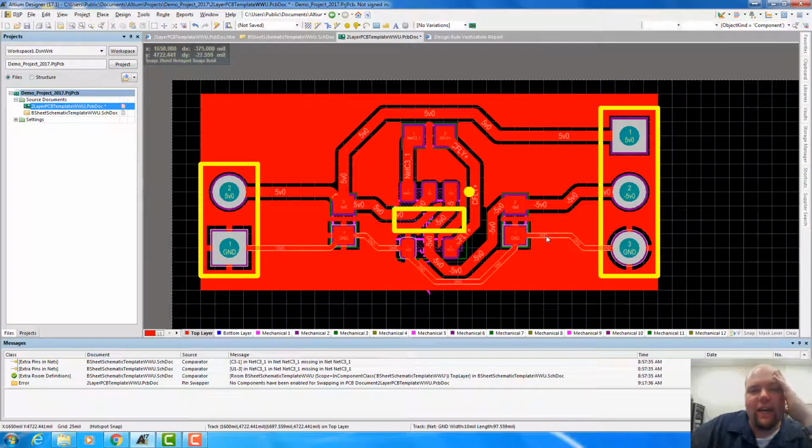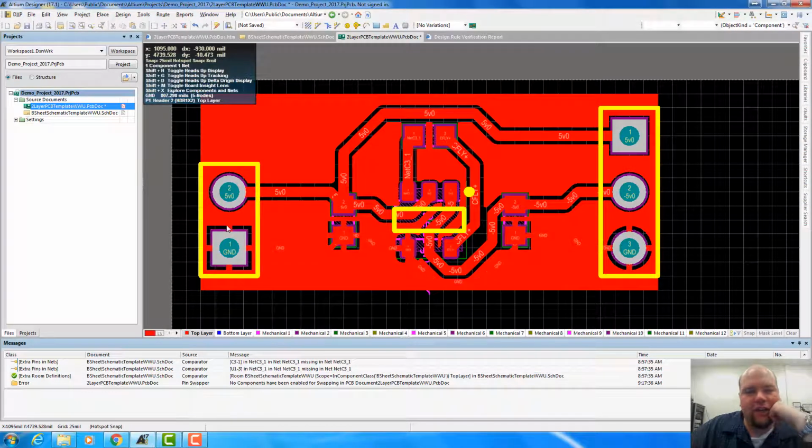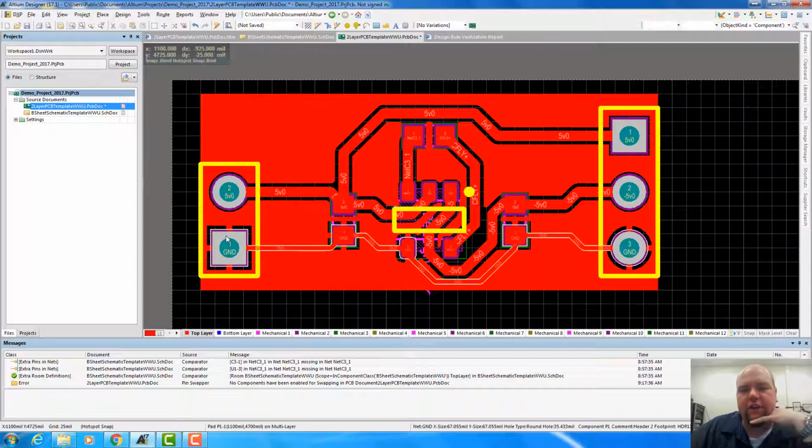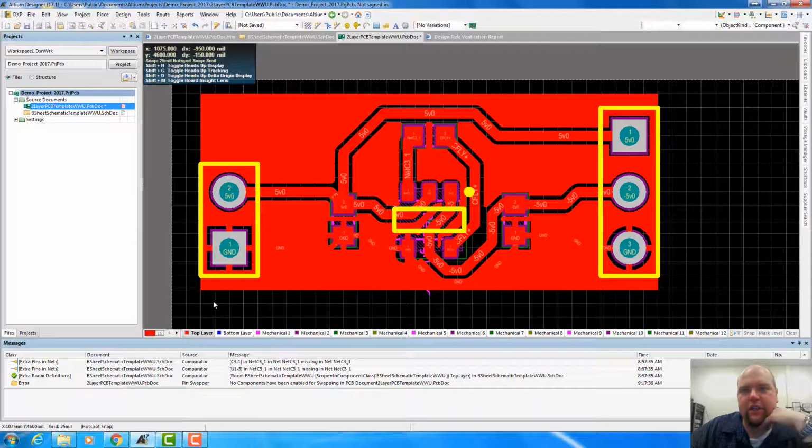So why does it have these little connections here? Our pads are only connected by these little crosshair connections. That's called thermal relief. The problem is that ground planes are great electrical conductors, but they're also great thermal conductors, and having a good thermal conductor is not always a good thing. Especially if you have a through hole here where you're going to solder a wire.